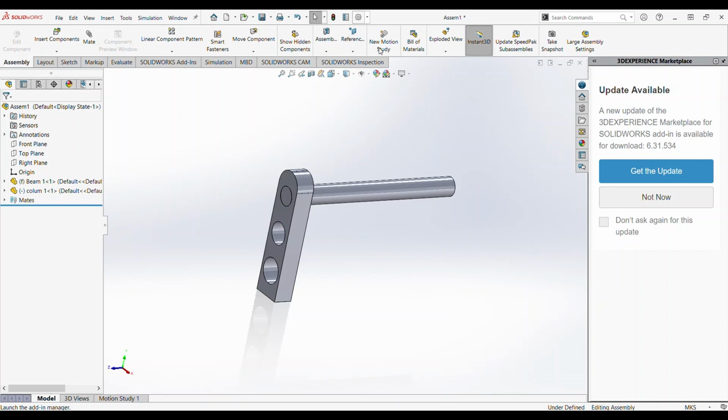If you go to the add-ins, there are all the add-ins that are not selected or not automatically brought to your user interface. When you wanted to use it, just click here and click OK. Then it will pop up in your main window.